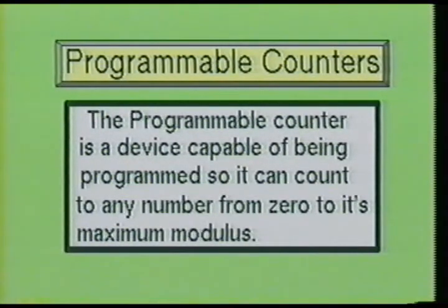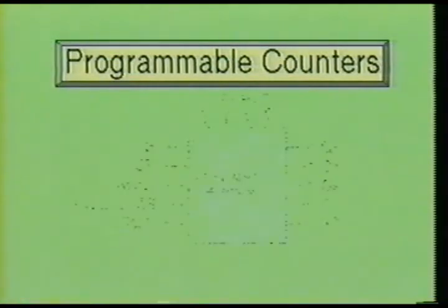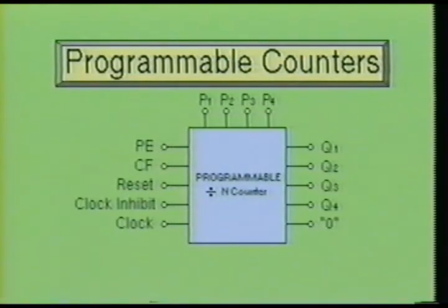By presetting the stages of a counter, you can design a circuit that in some cases will count either up or down, because each separate stage can be made to reset when the preset count has been reached. Here we see a typical programmable divide by n counter.